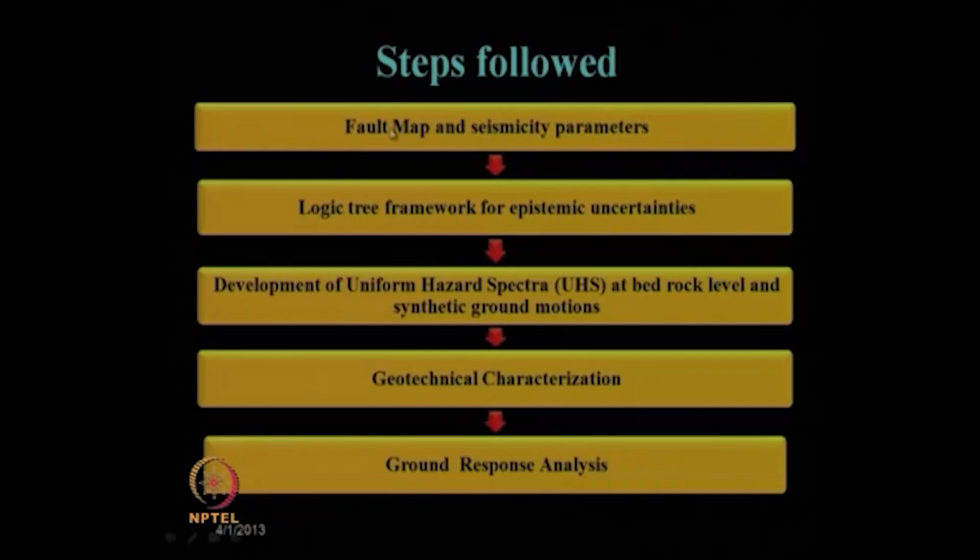What are the steps followed? The fault map and seismicity parameters are known, and the logic tree framework is already used. Then we developed UHS at bedrock level for the synthetic ground motion. Then geotechnical characterization is necessary for each port site to carry out the site response analysis, which will finally give us the result for this site response or ground response analysis.